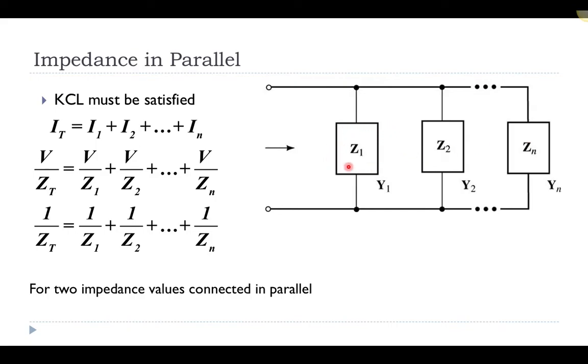So remember that the impedance values here can be combinations of resistors, inductors, and then we're also going to have capacitors as well. So there's a box here because we don't know exactly what components those are inside. If we apply the equivalent of Ohm's law for impedance, we know that the total equivalent current can be written as the voltage divided by the impedance. So I could take this complicated circuit and reduce it down to a single impedance value connected to a single voltage supply with a current running through it.